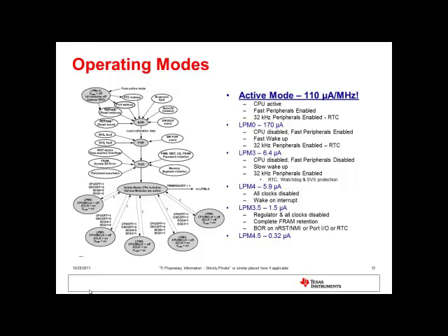This slide shows the operating modes and the reset sources for the MSP430. The system reset sources include a brownout reset, a power-on reset, and a power-up clear. Different events trigger these reset signals, and different initial conditions exist depending on which source triggered the reset.